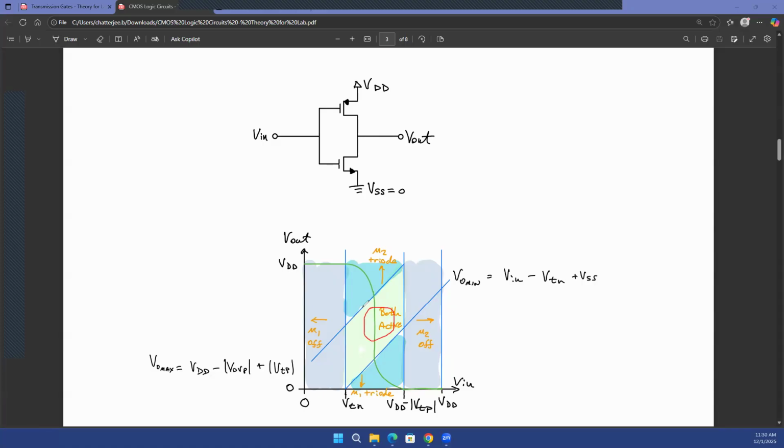Question? Yes, it does happen very quickly. You're right that you may not have an instantaneous switch. The switching may itself take some time. And we learned about the concept of slew rate, right, when you are talking about op amps. So slew rate actually tells you how much time it takes to switch.